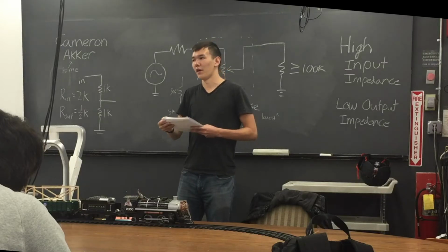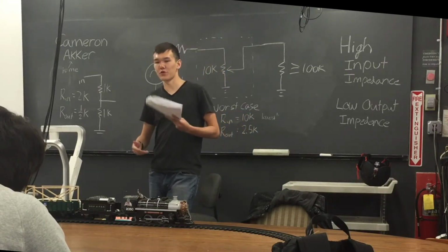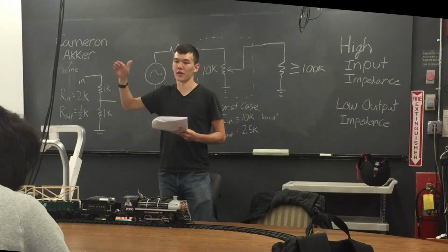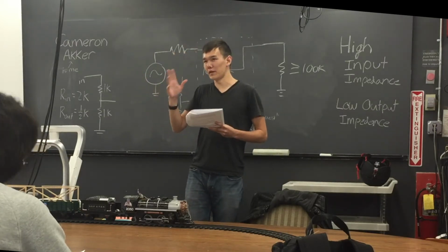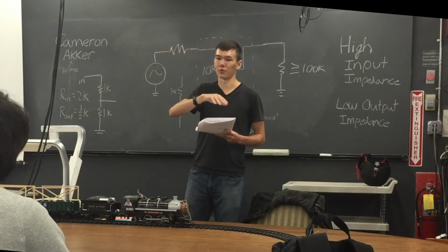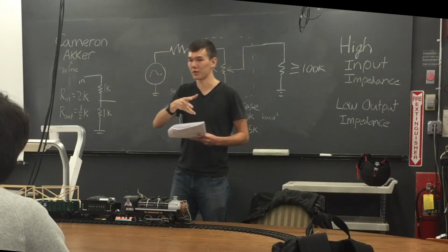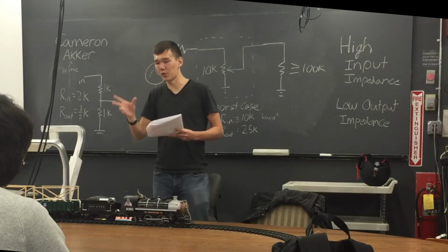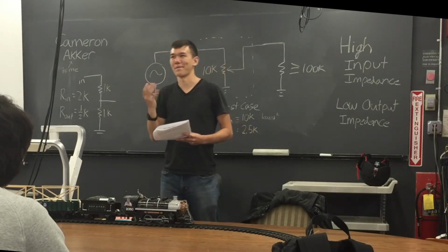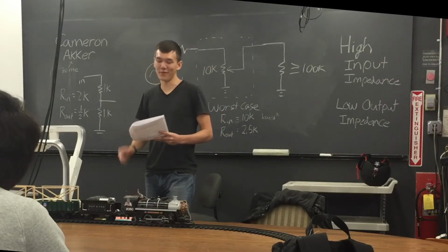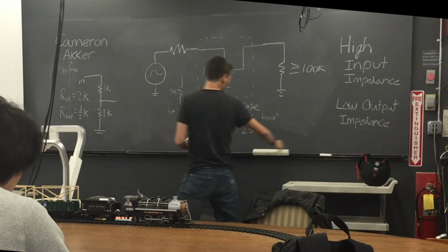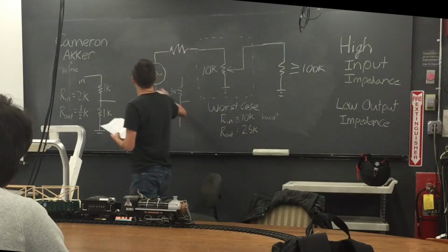That's the reason. To simplify things, we usually say you're passing through the difference in voltage to the other side of the capacitor, and that's true in the sense that the current on the other side is proportional to the difference in voltage, and the current eventually accumulates that voltage. The problem is the current doesn't accumulate enough voltage to the same amplitude as what you put in. If you look at the equation, I equals C dV/dt, just throw it up there.